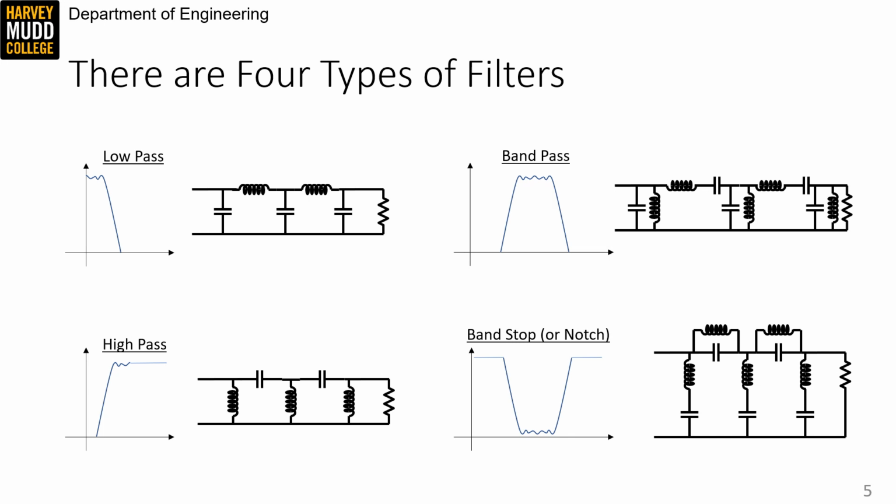Consider the low-pass filter as a starting point. At low frequencies, the capacitors are open and the inductors are shorts, allowing the input voltages to reach the load easily, and at high frequencies, the capacitors are shorts and the inductors are open, which zeroes the voltage on the load.